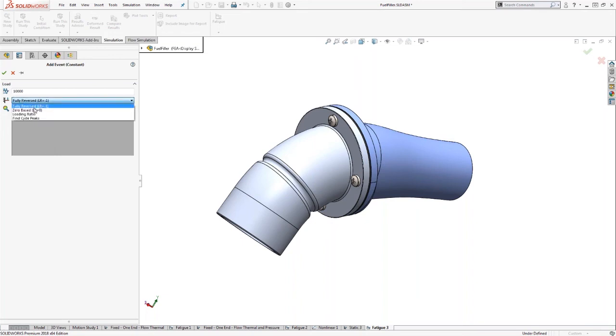So in this case, I'm just going to assume this zero-based type of activity, where it's not constantly running, or it's only running after a certain number of times, but then we're shutting off the fluid, that on and off type of activity. And then we reference what study we want to reference the stresses from, so it can determine what the alternating stresses are. So I choose the study name there.